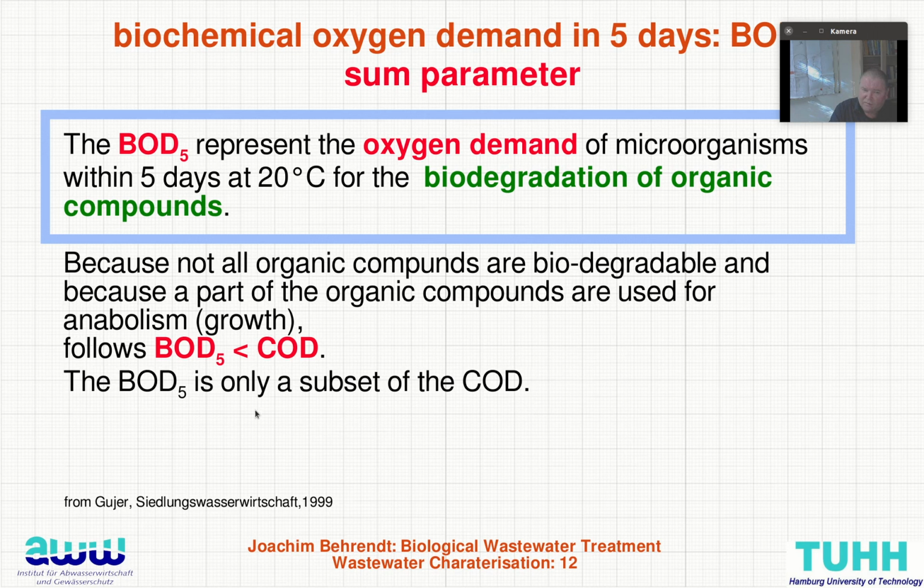Finally, this parameter is frequently used for the description of biodegradation or not, but this is very dangerous. Normally, if this relation of BOD to COD is 0.2, oh, this is not biodegradable. But finally, you always have to make a test with adapted microorganisms to be sure whether this component is degradable or not.